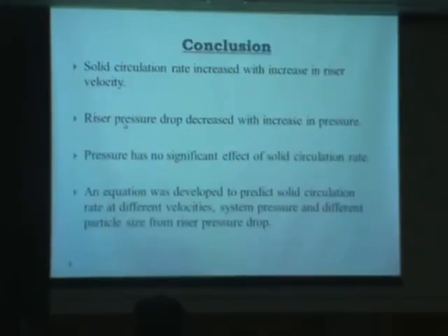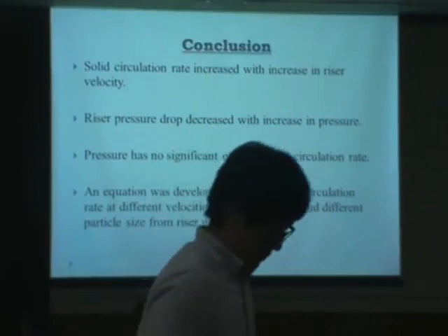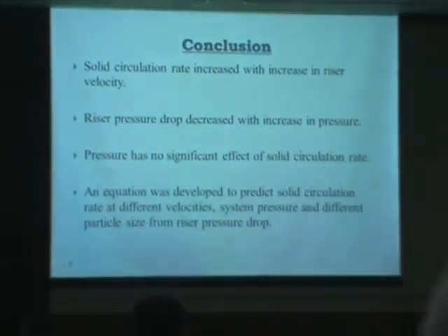But at least we have developed a non-invasive method to calculate the solid circulation rate at high pressure conditions, because all the previous studies were conducted at atmospheric conditions. You have observed that pressure has a tremendous effect on riser pressure drop. It decreases with increase of pressure. That's why we attempted this study to develop a model at high pressure.